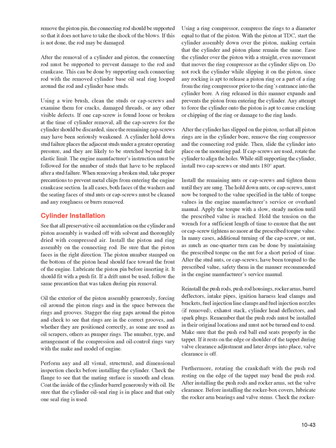Perform any and all visual, structural, and dimensional inspection checks before installing the cylinder. Check the flange to see that the mating surface is smooth and clean.